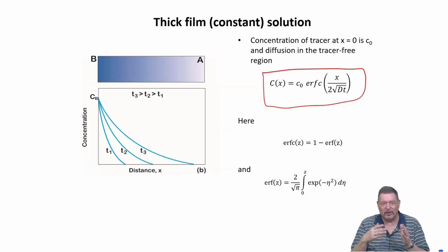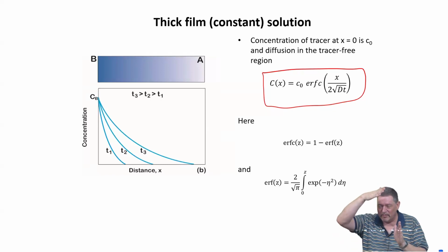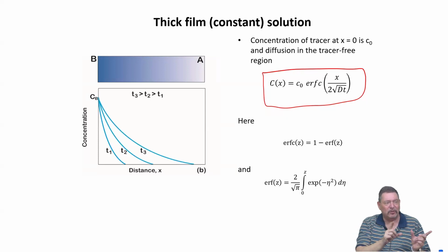Because in the way you will then separate the material, we will count how many atoms have diffused up to which depth. This gives you a diffusion profile, but the way how you fit the diffusion profile to obtain the diffusivity D will depend on your boundary conditions in the experiment. If you don't know them, maybe you evaluate it in the wrong way. So if you apply an error function solution to a situation where a Gaussian solution would be appropriate, you get the wrong D. So it means that you really have to test and think about how to set up and plan the experiment so that you know how to evaluate the data in the end.